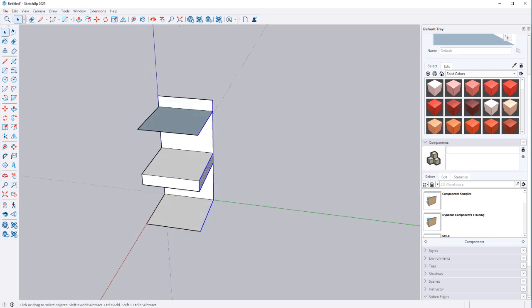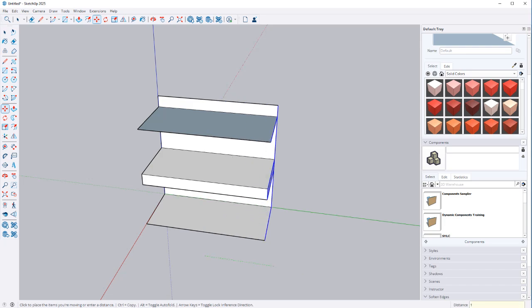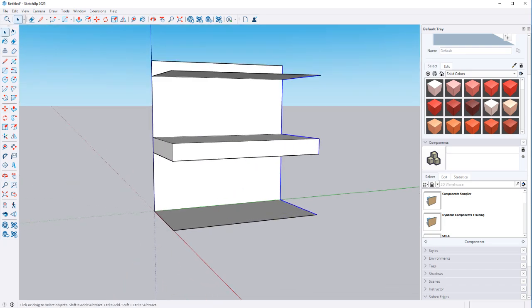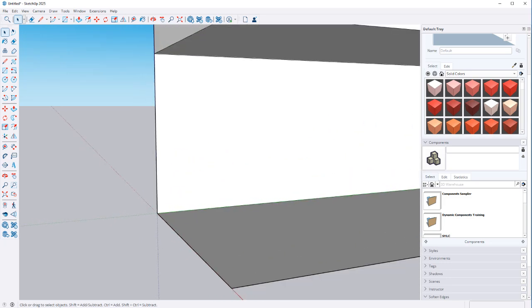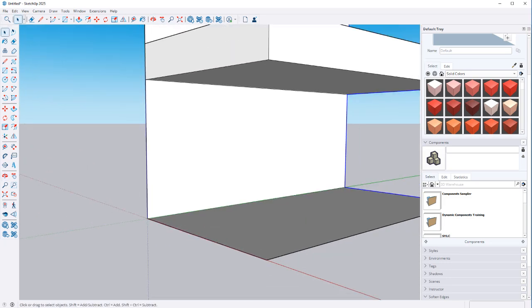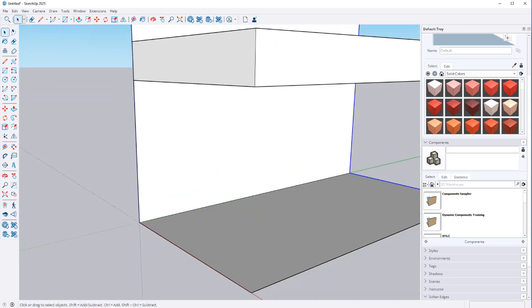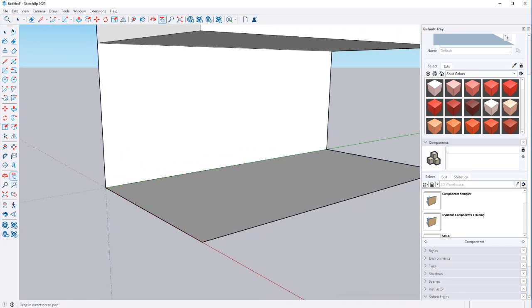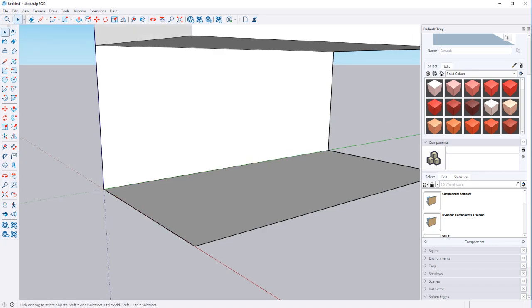I'm going to grab these right here and run this out another 10 feet, because stairs take a lot of length. To figure out my stairs, I'm going to draw them here in SketchUp. The rule of thumb for stairs is rise over run. We talked about rise over run with the roofs, but with stairs we're going to be doing 7-11, right?